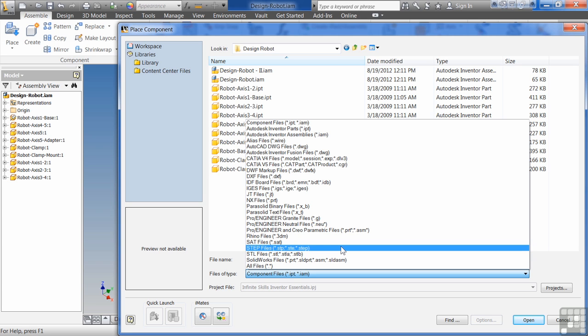If you save it out as a STEP or you import it in as a STEP, it's a really good way to get files into Inventor. I've also seen issues if you bring in a CATIA or a UG file, for example. Sometimes what'll happen there, if it's a sheet metal part, there's not enough gap in between the parts. It wants to use the exact same face. And so Inventor says, whoa, whoa, whoa, that's physically impossible. You can't do that. These guys are breaking the laws of physics when they unfold their models.